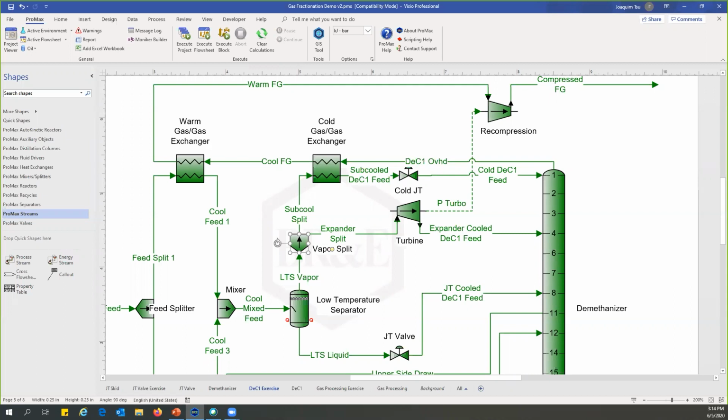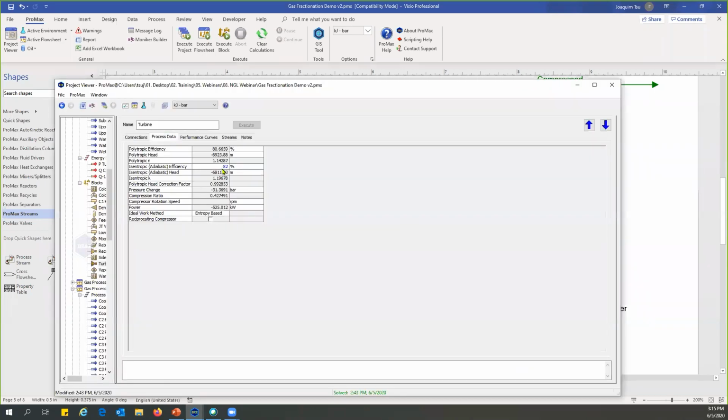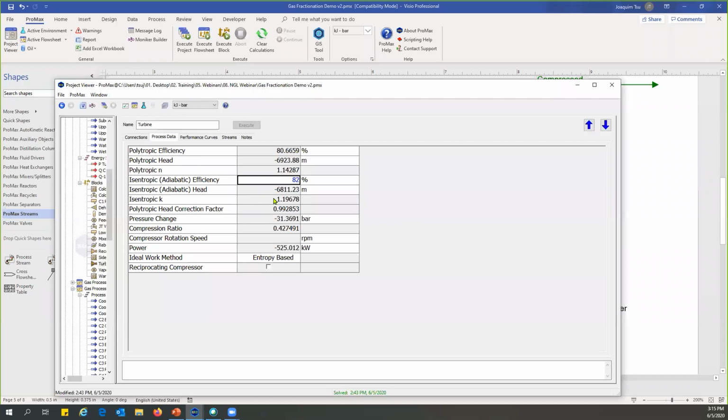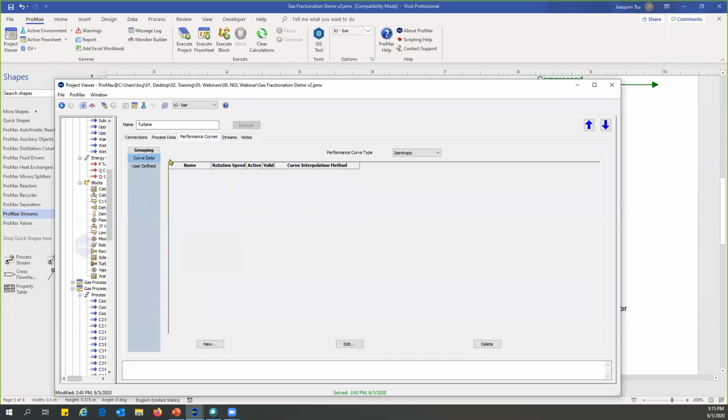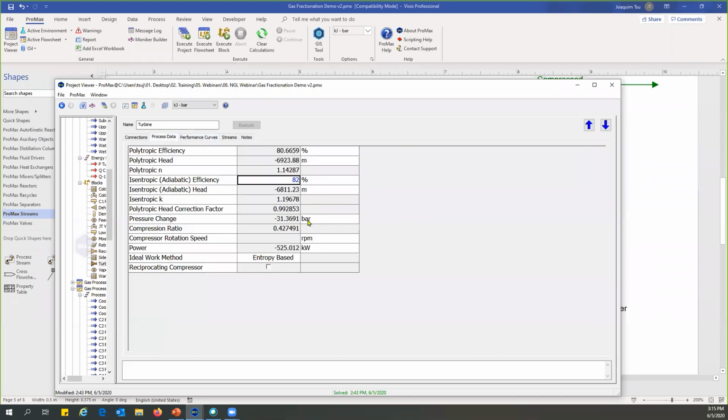So next, what is the turbine efficiency you have considered for this simulation? In this case, the turbine efficiency I have used is 82%. This value can range anywhere from 70% to 95%, I've seen. But if you did not know what your efficiency here is, you can always put in a performance curve. And then using the performance curve as well as your actual flow rates, we can tell you what your efficiency should be. So that's one way of doing it. But generally speaking, I just use a value from 80 to 90% if I'm just doing a quick model.